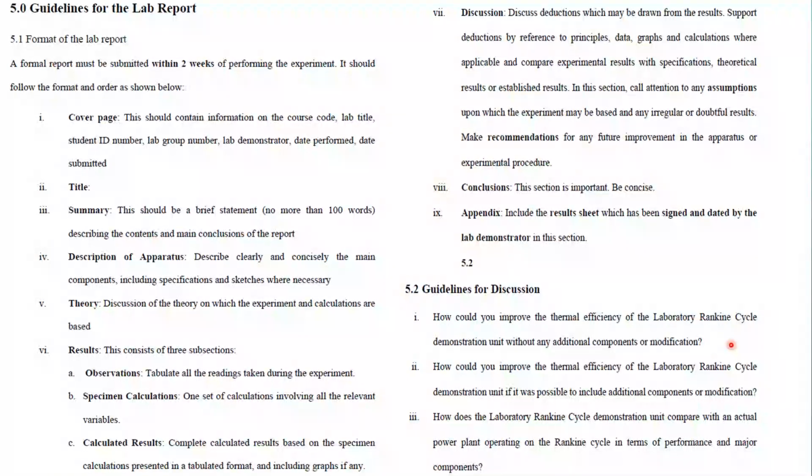This increase in dryness fraction would mean that the moisture content in the steam is a lot less. So if the steam has a lot less moisture in it as it passes through the turbine blades, it will reduce the risk of corrosion on the turbine blades. So that's one thing you'll want to do: ensure that the steam leaving the boiler is superheated to a higher temperature before it enters the turbine.